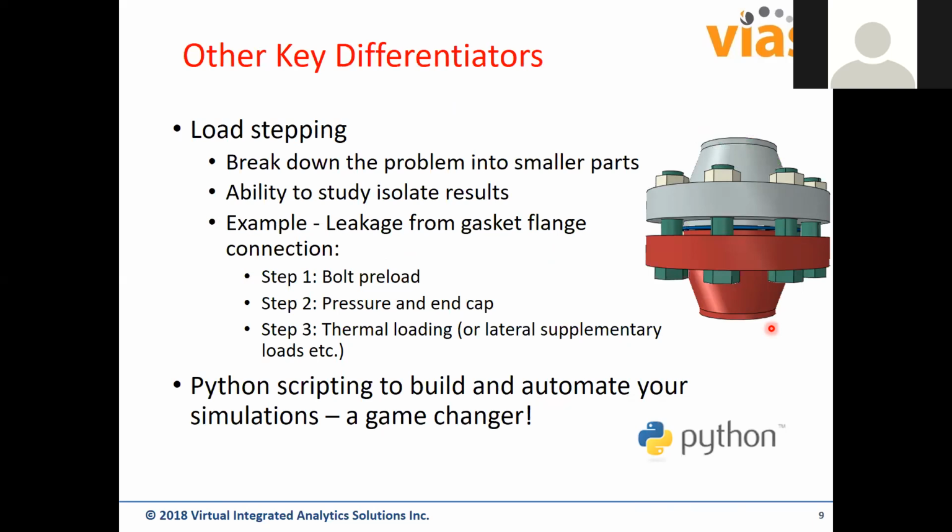material, as the connection continues its service, you could either see lateral supplementary loads because of an external effect, or you could see thermal loading. Each of these, you could replicate exactly the way they would occur during their operation. And also, you are able to get snapshots of what's going on between these steps. So if you want to look at how much preload I have within the gaskets when I tighten the bolts, you can get all of that between the steps themselves.